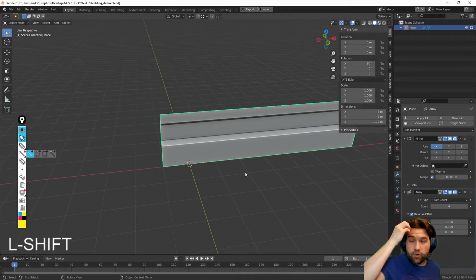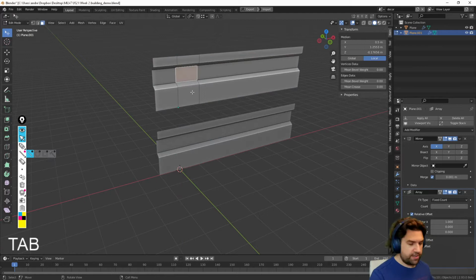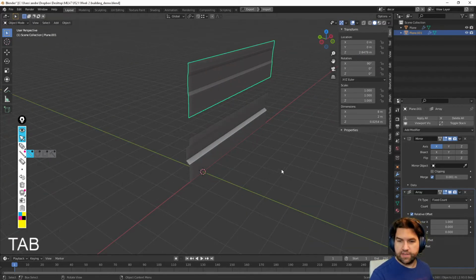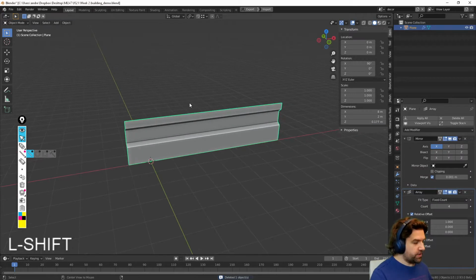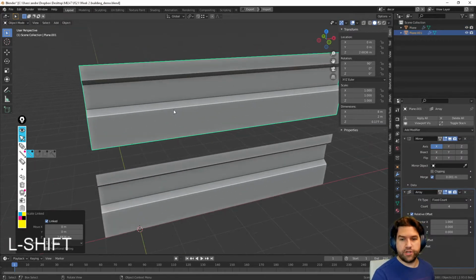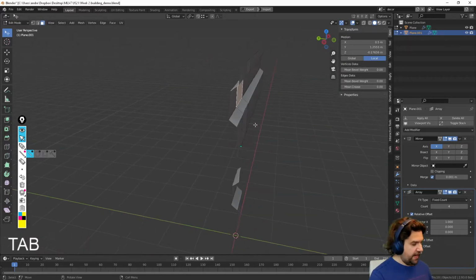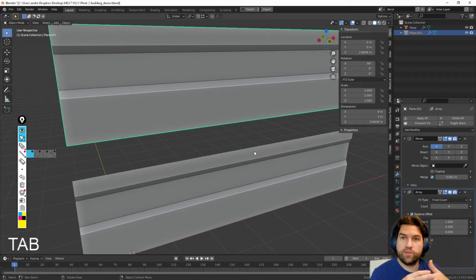Now, when I want to build a corner, of course, I can try to take this and fuse the parts together, but I can use the mirroring tool to my advantage. So another thing I can do is if I hit Shift D, I have a duplicate of this, and if I change or edit stuff, it doesn't change this version. But if instead I use Alt D, what I'm creating is what's called a linked version. And what's cool about a linked version is anything I do to this happens to this too. This is really great for elements we know are repeating.